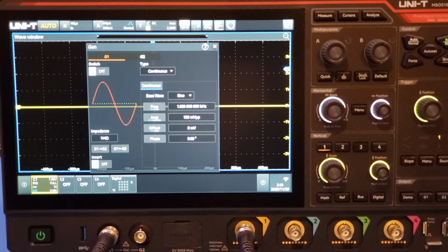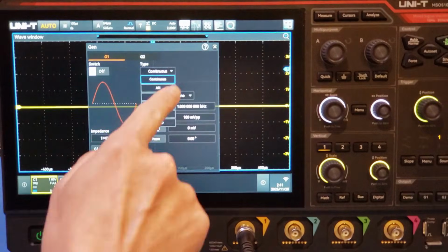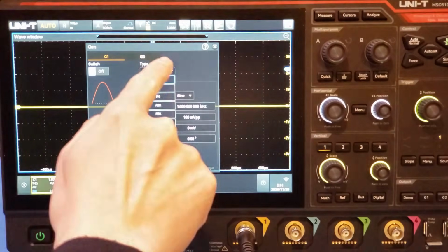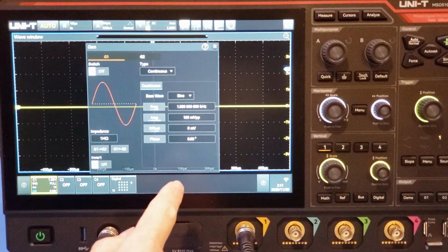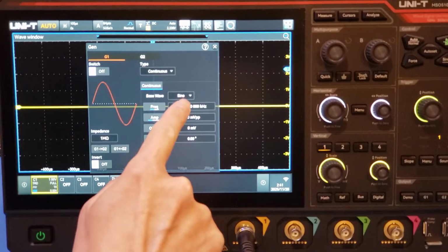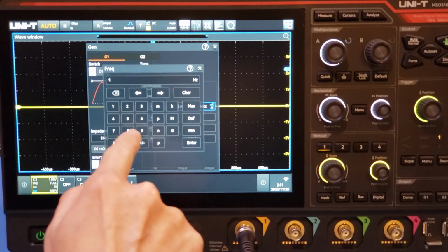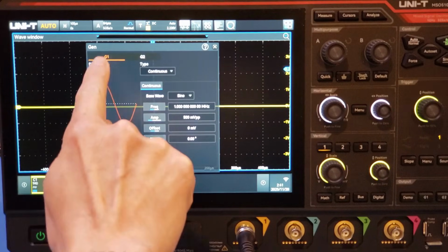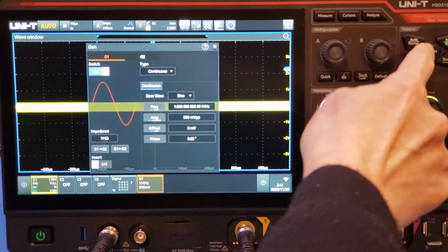I think out of the box, it gives you a few weeks of trial period. Since I did not enable the arbitrary waveform generator, what we're looking at here is essentially just a function generator. But even the function generator, you can see, is actually still pretty good. We have continuous waveform. You can see here, you can do AM, FM, ASK, FSK, and sweep. So let's take a look at a sine wave. Let's generate, let's say, a 1 megahertz. Let's enable it. So let's acquire the signal.